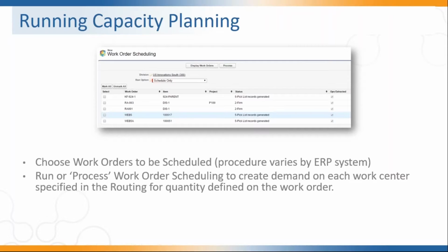And typically, the determination as to whether you would schedule a user or schedule the machine is what is the limiting factor. Which one of those two things could cause a bottleneck in that particular work center? If we only have one machine, then you can only run one job. Even if you have 10 operators, only one job could be run at a time. So that would be the limiting factor, and a planner would want to know just how heavy is the burden or demand for time on that machine.